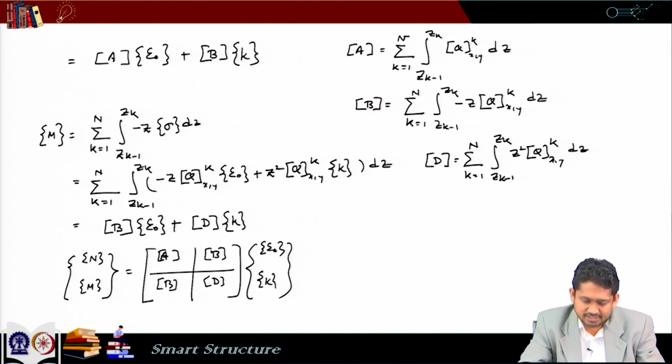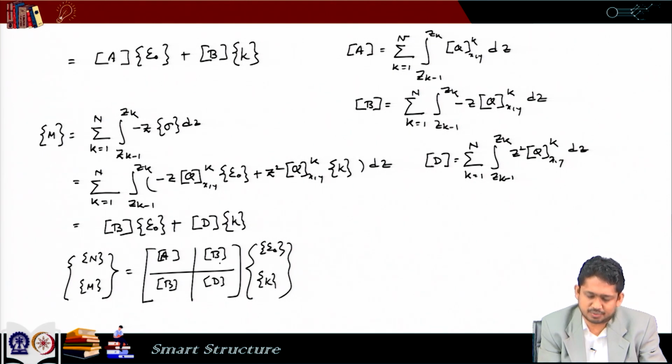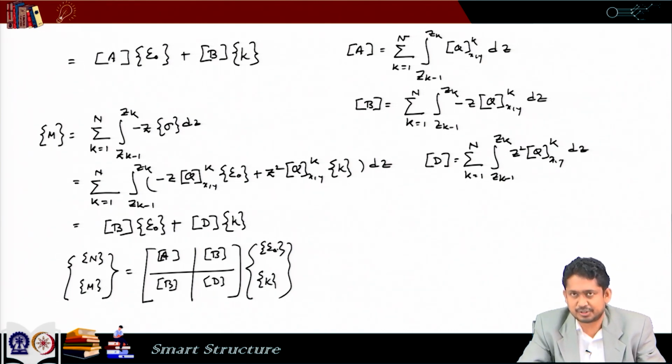Okay. So, for example, we can see here that this B matrix relates the in plane force components with the out of plane displacements, because these are the in plane force components, these are the bending moments. Here we have epsilon 0, it has u 0 and v 0 only. So, again it has in plane displacement components, and kappa has out of plane displacement, which is w. So, u v w are displacement along x, y and z, and u 0 v 0 are the mid plane displacement components, and w is the out of plane displacement component.